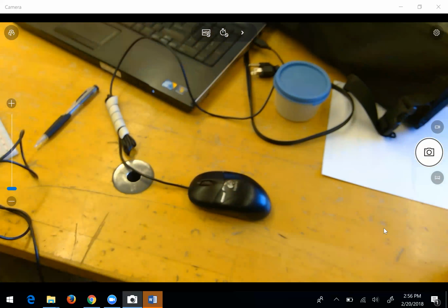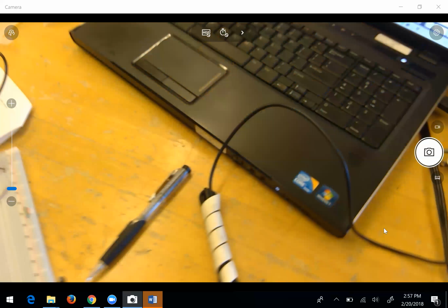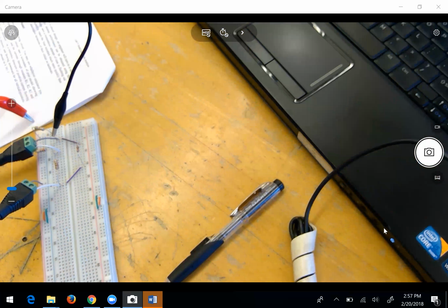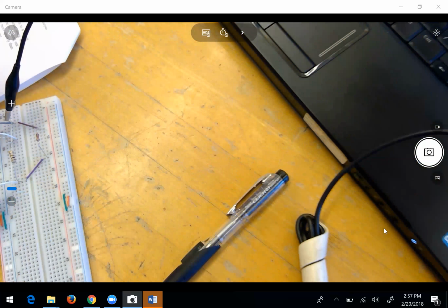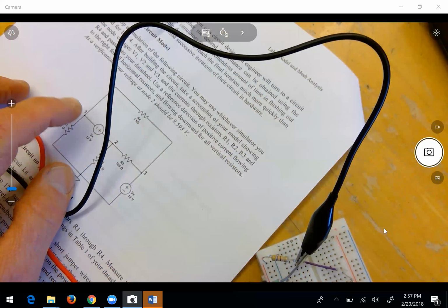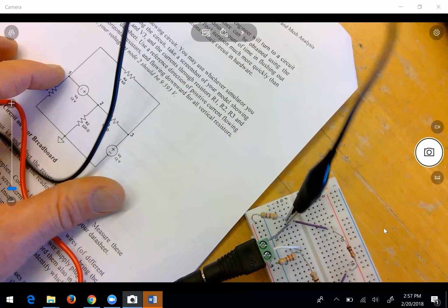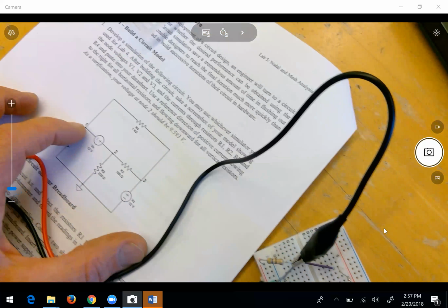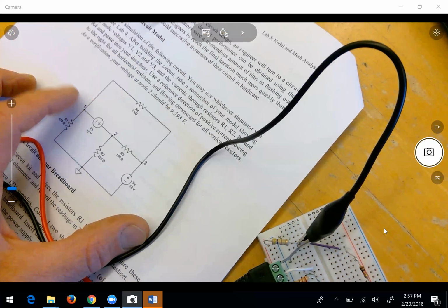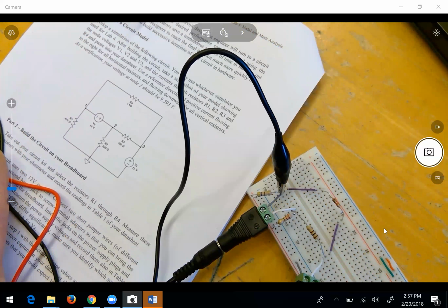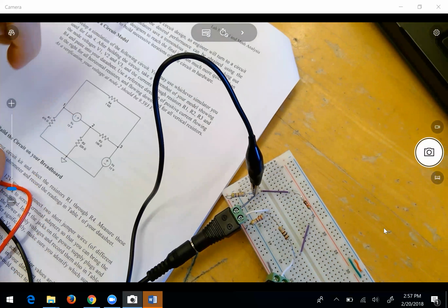Where do I click these on? To do what? To measure V1, V2, V3. The node voltages? Yeah. At the node? Yeah, but remember what the node voltage means. The node voltage, this is the voltage of this thing relative to what? Everything around it. What do you mean everything around it? This and this? Nope. We call this node 1, and that voltage is relative to what? I would assume this voltage source there and the resistance. Nope. It has nothing to do with those.